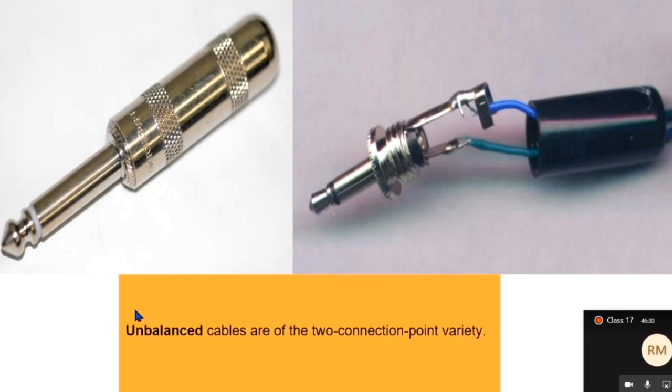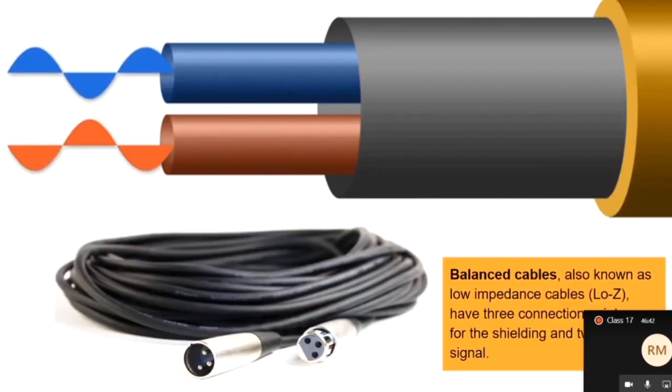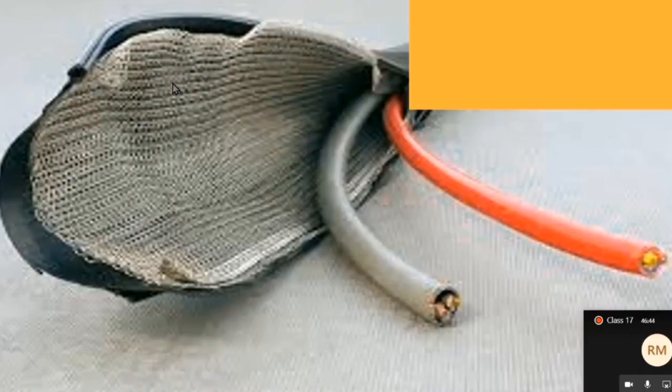What is it transferring? It's transferring signal, like your analog signal, and it's transferring a ground. And this picture here shows you what the ground is. This is a mesh that surrounds the inside of the cable. And that mesh is designed to preserve your analog audio from the bombardment of cell phone signals, radio signals, television signals, CB radio, the electromagnetic spectrum.